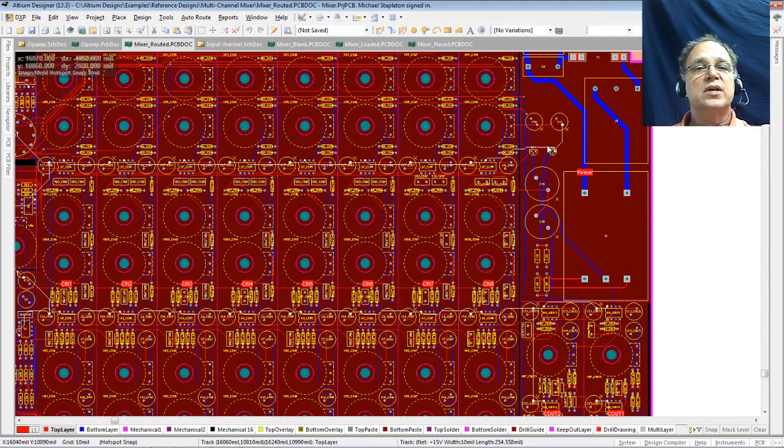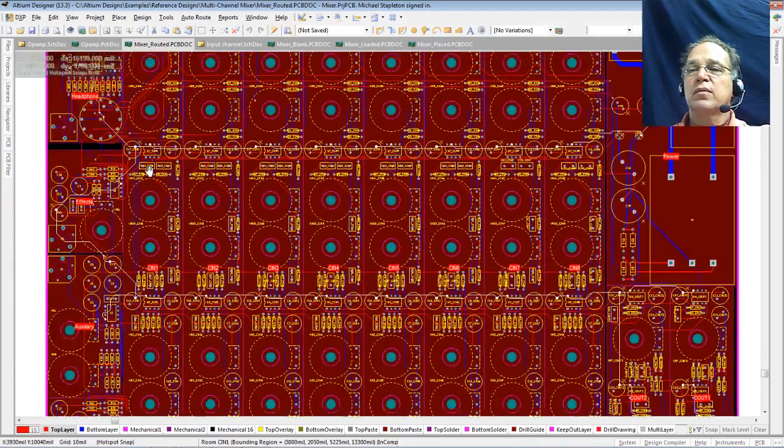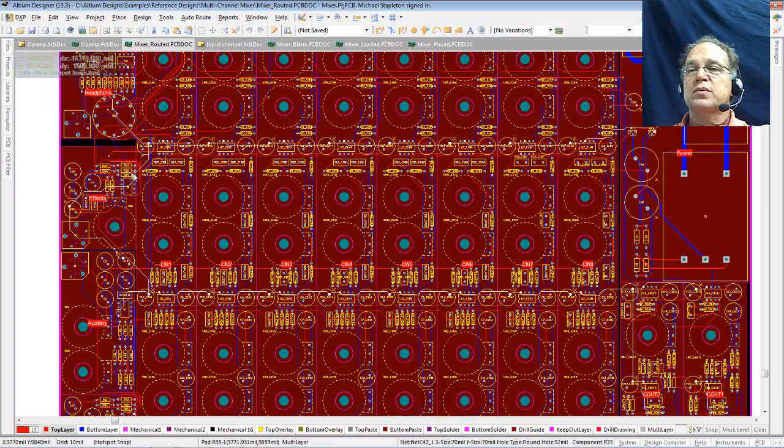So everywhere you see this white line, and you'll see my mouse is following it, is 15 volts. And you'll see that little trace. It's only 10 mils, that's 10 thousandths of an inch wide. Here it comes down here, comes over here, comes over here.